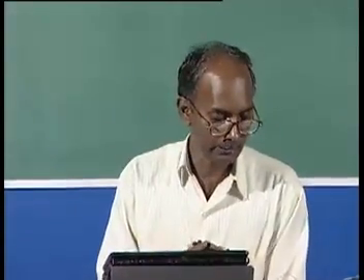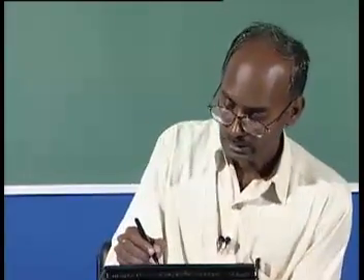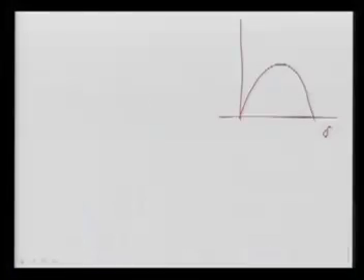Now let us see another major difference. When I was talking about the P-delta curve, if you remember, this is your delta, and this is without compensator. If you compensate, ideally we go to double this. When there is no limit in the midpoint compensator, then we will achieve this P-delta curve. This is without compensator, this is with compensator.